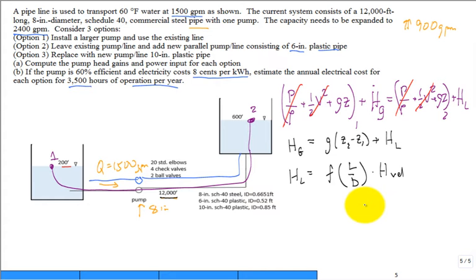Okay. Also, they have showing an inlet. Will there be a loss associated with the inlet? Yeah, and it's protruding in, and we'll just assume it's sharp-edged. And do you remember the loss coefficient K for that one? Yeah, 0.07,